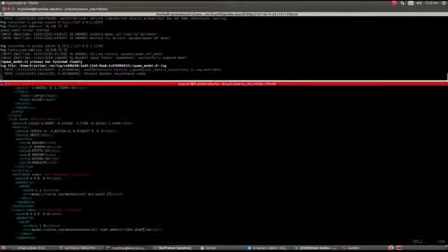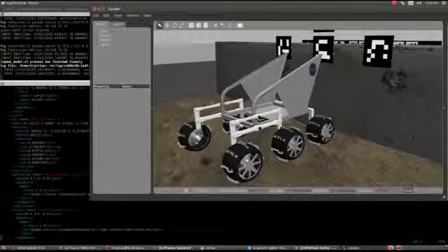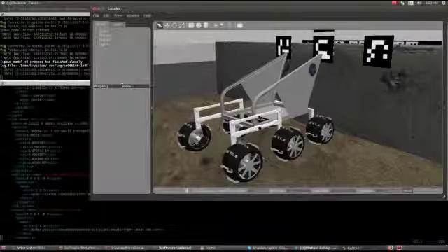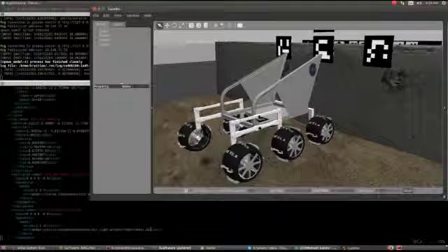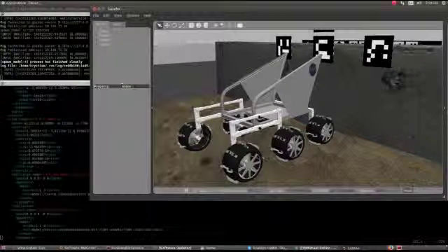For the visual, we want to specify the DAE, and I just used the DAE for the right wheel for all the wheels, and then just rotated them as necessary, as they would show up in different orientations when placing them and applying the DAE for the visual mesh for all the wheels. So all you need to do is apply a rotation, take out the negative sign. It's a bit of playing around. You don't necessarily have to use the right wheel. I did it for simplicity, where I could copy and paste this and just take out the negative sign. But it's just user preference.